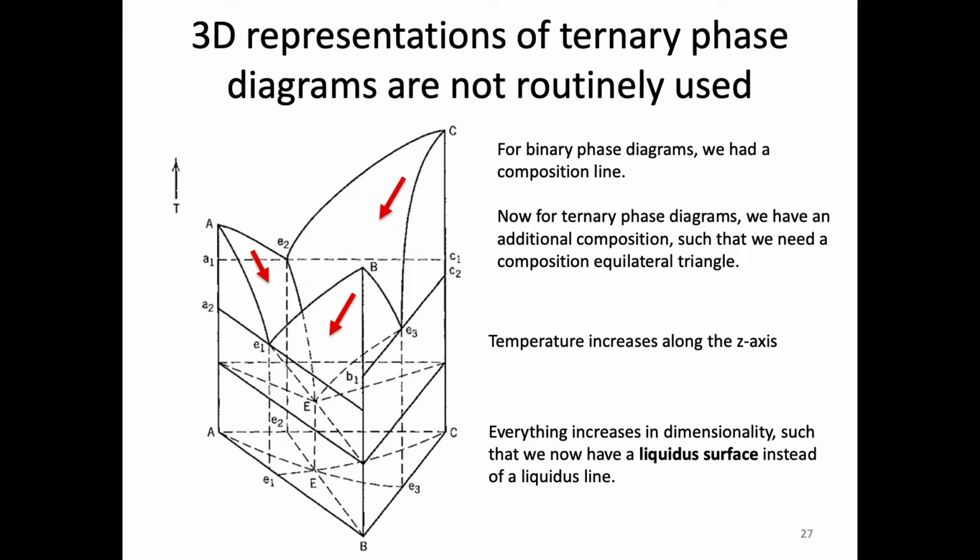And so this is a representation of a eutectic phase diagram in the ternary space. So again, it's a 3-dimensional thing, which is hard to represent on a piece of paper like this. But one thing you'll notice is that there's this big surface that flows down towards the middle, and the same thing over here, and the same thing here. And it all flows down to this point right here. So this low melting point temperature known as a eutectic. Right? All the end member components A, B, and C have higher melting points. So that's the classic hallmark of a eutectic system.